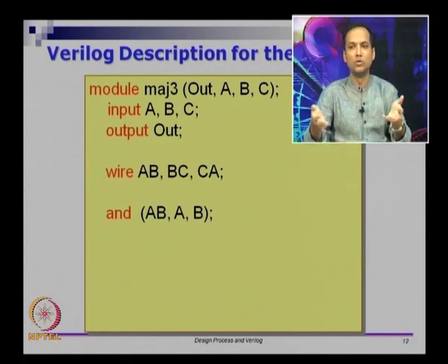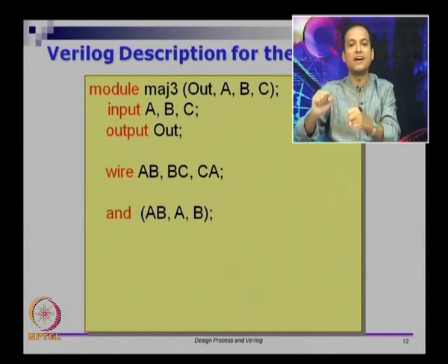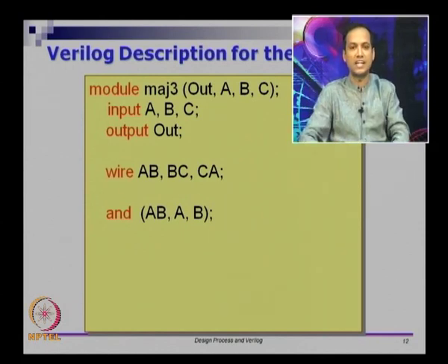This is what you would do if you do this in a breadboard, right? You would go and pick an AND gate and put it on the breadboard. You will connect two inputs A and B to it, and wherever the output pin is, you will take that and keep it dangling for a while. So you know you want to use this later, you will keep it dangling.